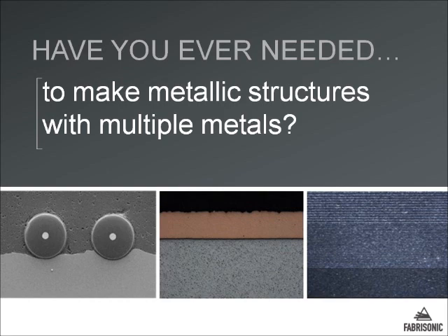The center is an example of cladding. We've taken copper and clad it onto aluminum. Cladding is often used to take an expensive metal A and bond it onto a cheaper metal B for things such as pressure vessels and corrosion vessels and oil and pipeline. We've done things such as tantalum to steel. Tantalum has about 10 times the corrosion properties of chromium and is very resistant to pitting corrosion. We've also done things like titanium to steel, where you want a thin layer of titanium to act as perhaps a diffusion layer or as a wear surface on otherwise steel structure.